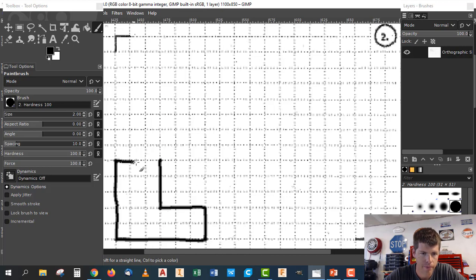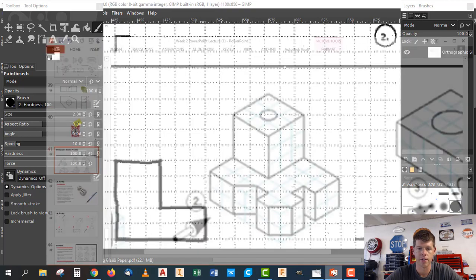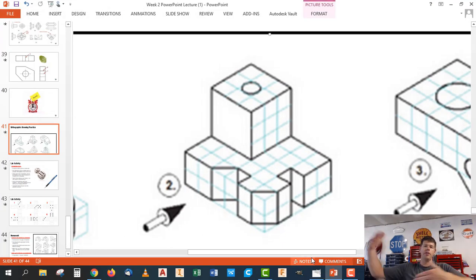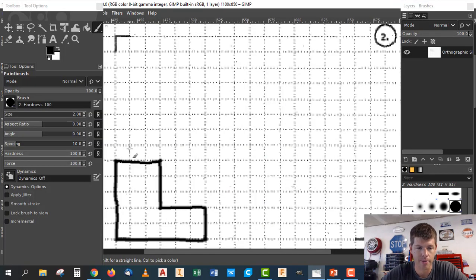and then straight over. Okay, so we're going to have some other edges in here also, but the thing you want to think about as you do this is when you draw that front face, imagine that the depth perception of everything, if you take it and shift it all to the same plane, you're drawing it all as if it's flat. You can't see the different depths and things until you look at the right view and the top view, but in the front view, all those different distances behind us, you're going to take those and bring them all forward and draw them in one flat plane. And that's what's kind of tricky about some of these.